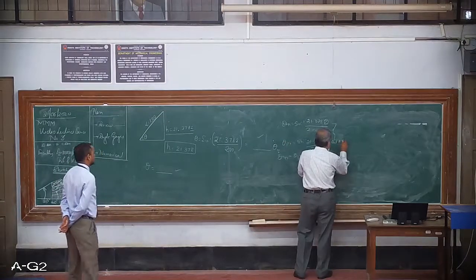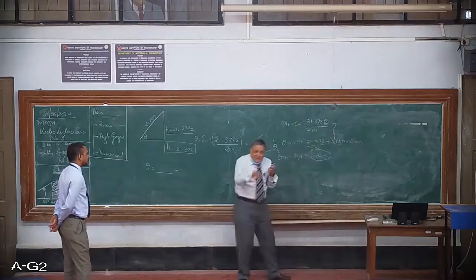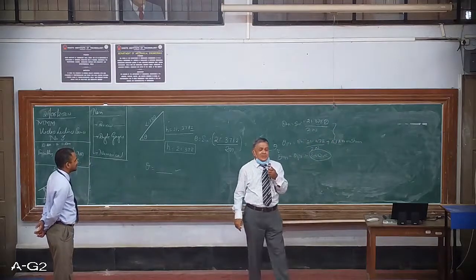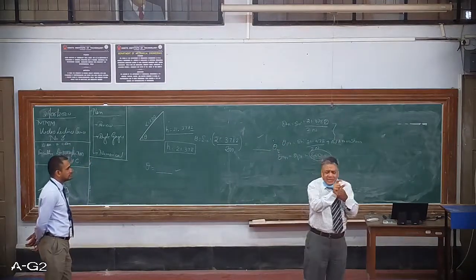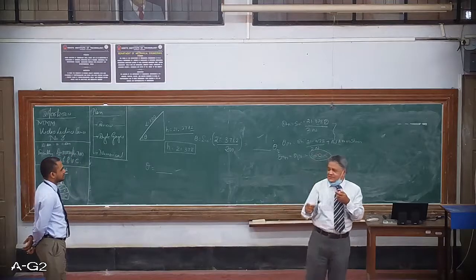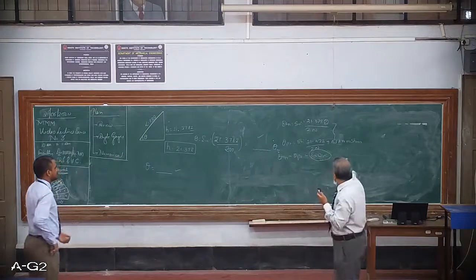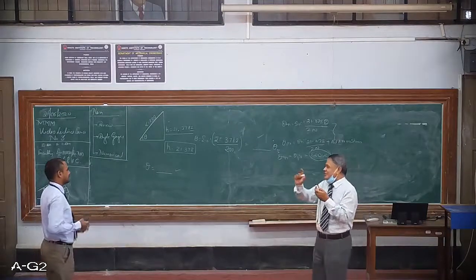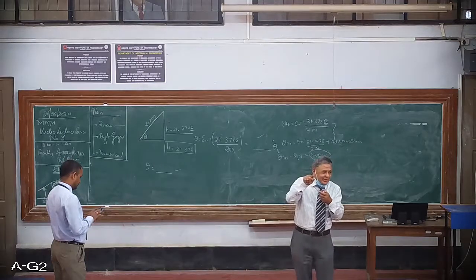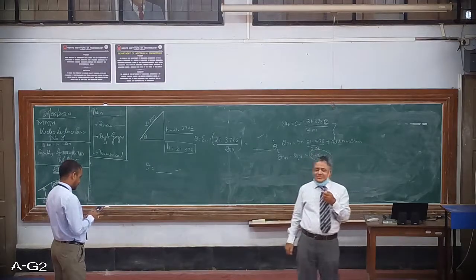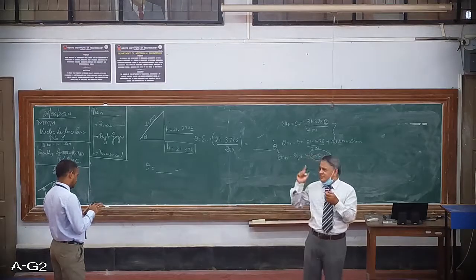In industry, some minute micro shims are available. Then you have to add micro shims and set the value correctly. So it again depends on the practical situation. If I can sustain that error, maybe in terms of a fraction of a second, then it is okay. But if you still want it correct, say for example I want to set the angle gauge here and I cannot sacrifice even a second, then you will have to use the micro shims and build that angle.